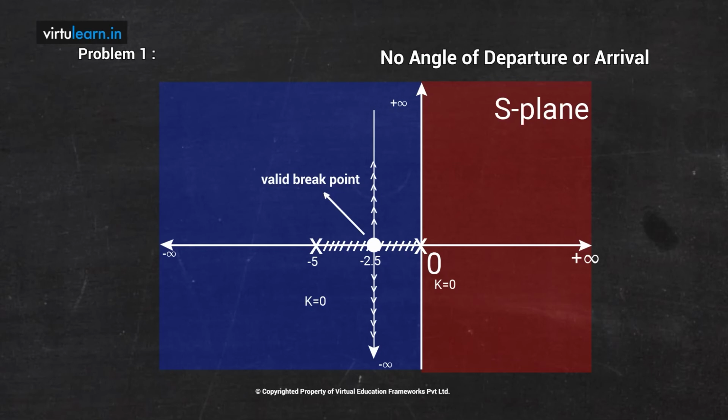So this pole cannot move in the right direction because that is not root locus area, it is restricted. And it cannot jump into the complex plane because that point is not the break point. Only through the break point can a root locus branch jump into the complex plane. The right side there is no root locus area and it has only one possibility. That possibility is moving left. Therefore, this particular closed loop pole, as k is increasing, moves towards the left direction.